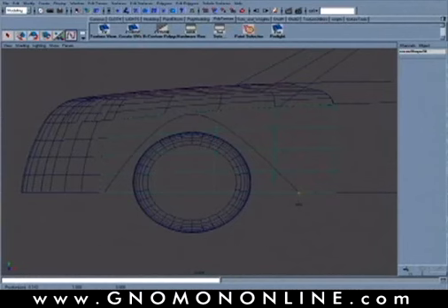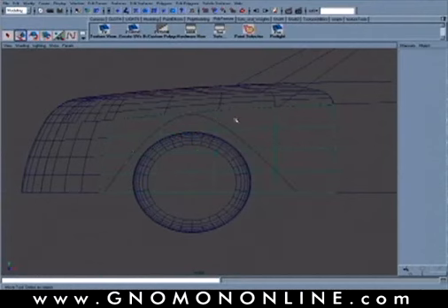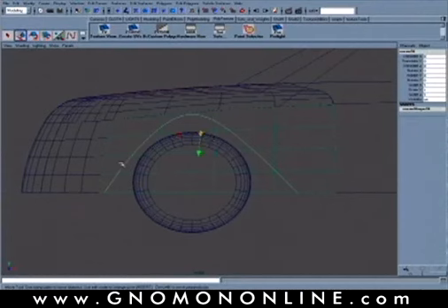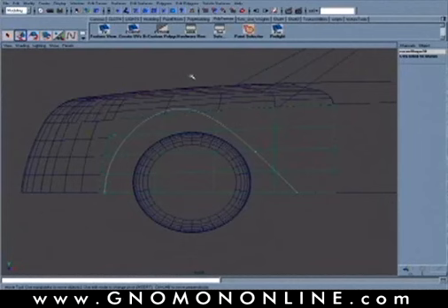Okay, now once I have this part created where I have my actual curve on surface there, you're going to want to start editing this curve on surface. So I can do this by going in and just grabbing CVs and manually moving or modifying where I want those points to be. Maybe in this case these are just snapped down kind of along the rim section here. And we can move this other one over to that side.